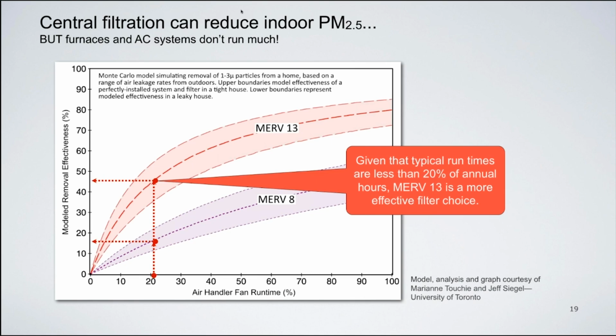Just as a side note to those of our listeners who are involved in HVAC engineering and design, especially for residences, part of the reason that there are short run times is that we tend in our HVAC community to oversize things. And when we oversize things, the system runs a short amount of time to satisfy the thermostat and then turns off. That means that all filtration ceases. So if you size things maybe less than the peak load, then you'll have lots more hours of runtime, which will be of significant benefit for filtration as well as humidity control.